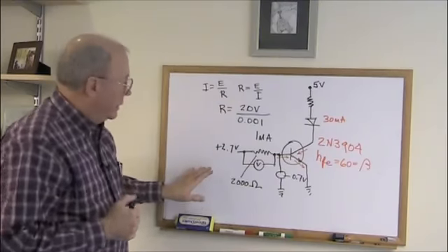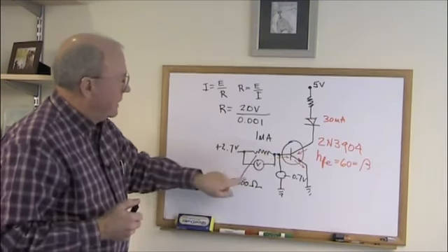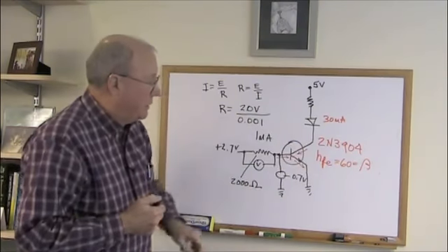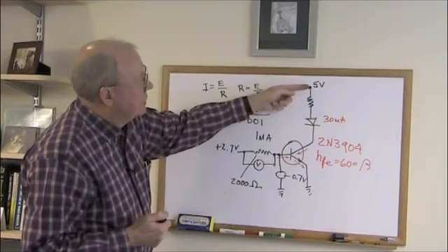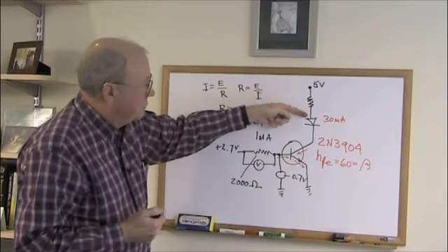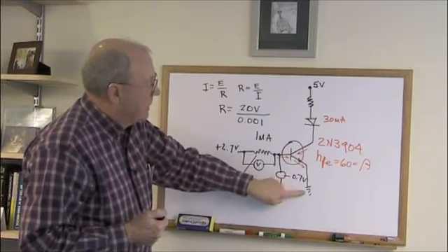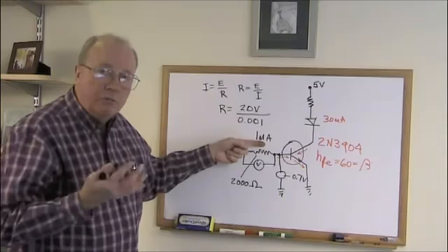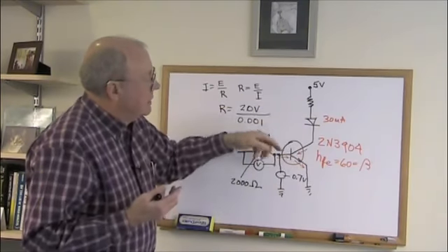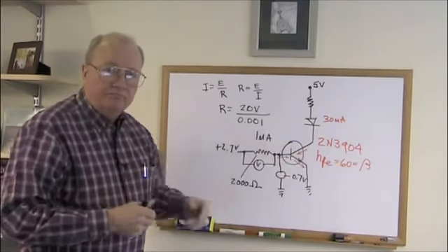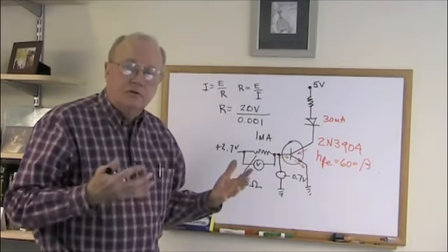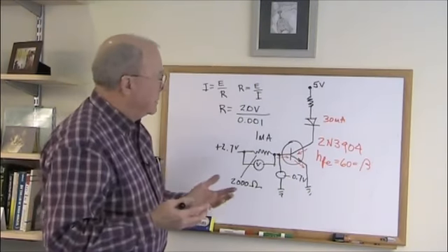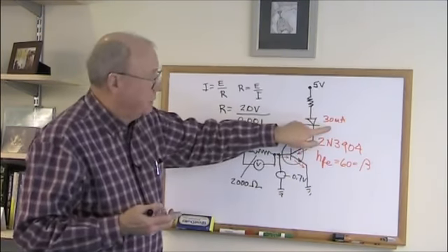So you've got a basic circuit here that you're supplying current at 1 milliamp into the base of this NPN transistor, which is a 2N3904. When you do that, it allows current to flow from the 5 volt supply through the resistor and the LED, through the transistor and ground. And you've essentially amplified current. You've taken 1 milliamp in, and for that 1 milliamp, you've been able to control 30 milliamps through the LED. So that's the basics of using transistors to drive LEDs. Find the data sheet for the transistors you want to use. Find the data sheet for the LEDs so you know how much current it will take, and you'll be in good shape.